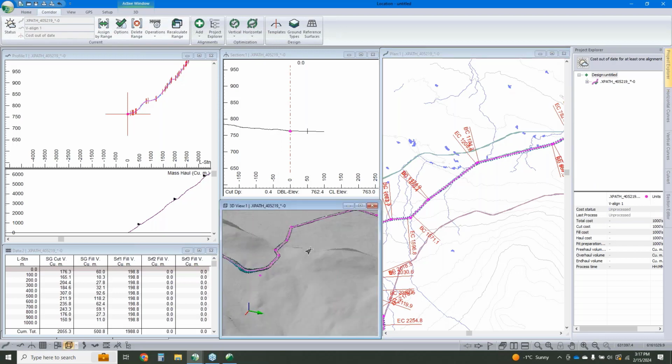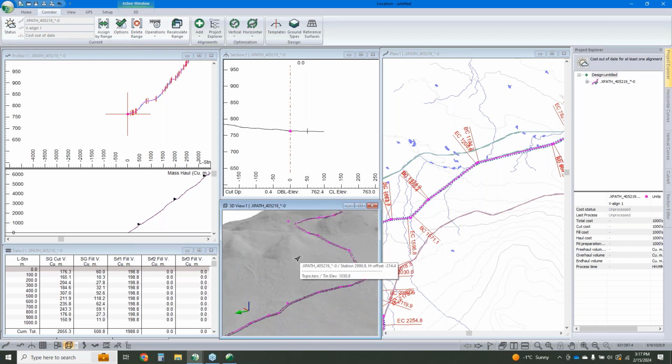But for this access road project, where we do want to minimize earthworks, we will, in the next few steps, start to show you how you can actually use that tool to reduce the cost. Totally. All right, so the polyline to alignment tool is run.